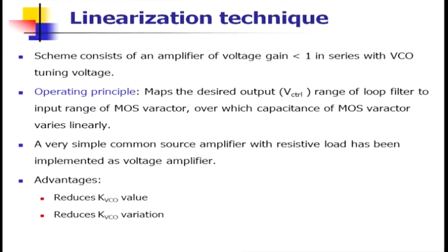So what you have to do is your KVCO, that is delta f by delta v, has a finite frequency tuning range, and for this kind of 2.4 to 2.48 you can easily calculate it is less than 5% of your center frequency. And then how are you doing it? Now you have a control voltage from the charge pump which is going to your VCO and changing the frequency, and there is a 4-bit control that is changing the switched capacitors, and accordingly bands are getting selected.